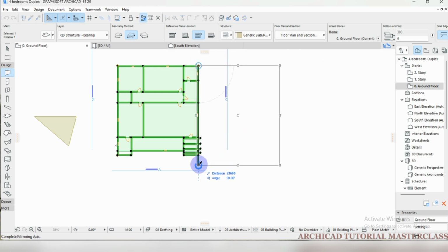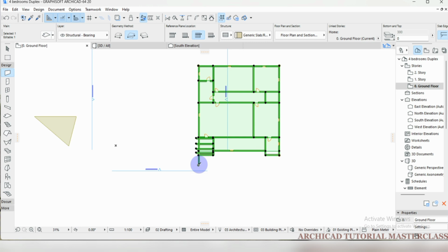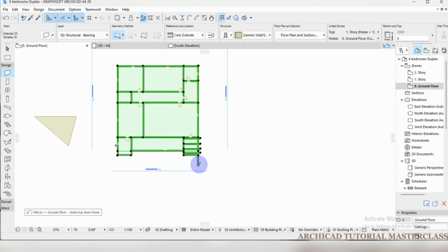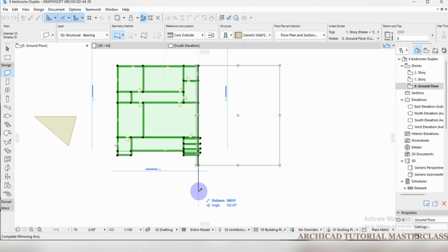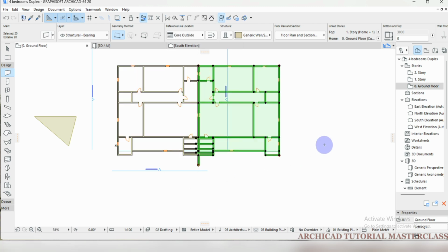But supposing that I forgot that it's going to mirror this way. Supposing that I forgot, I want to show you something. Control M. Supposing, oh, I forgot it was supposed to be a copy and I've already executed a mirror. So what do I need to do now? I'll just press my Control. The plus sign will appear. You see, it will still execute the command.